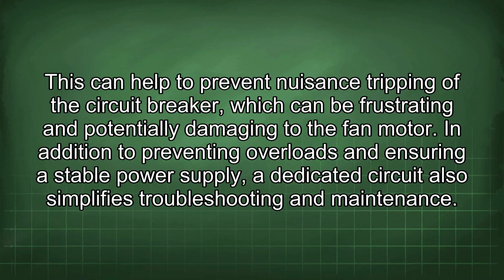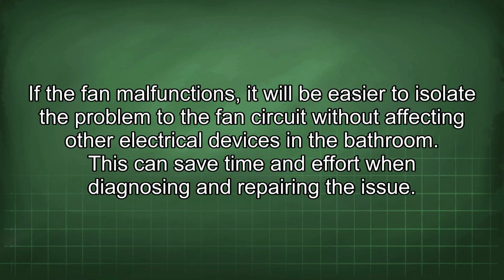In addition to preventing overloads and ensuring a stable power supply, a dedicated circuit also simplifies troubleshooting and maintenance. If the fan malfunctions, it will be easier to isolate the problem to the fan circuit without affecting other electrical devices in the bathroom. This can save time and effort when diagnosing and repairing the issue.